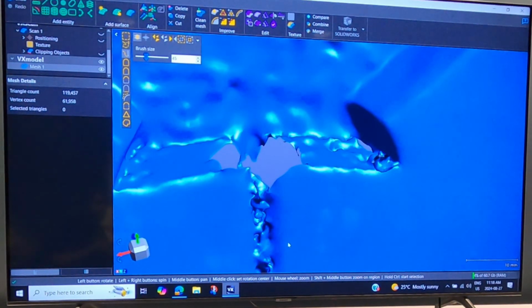That's interesting though, because in our case, we do want the imperfections, I think, because we're trying to replicate. Yeah, you're really trying to replicate. So in your case, you do a lot of auto surface, I think, and that way you'd carry over your model pretty much as is. Oh, really, there's an auto surface? Yeah, so you don't have to draw a rectangle. That's on the right, bottom. Oh, okay. That's right. As long as this is cleaned up enough to what you need it to be, you can just wrap it up in a surface, save that as a Parasolid if it's watertight, and then you have your solid CAD that can be worked from.